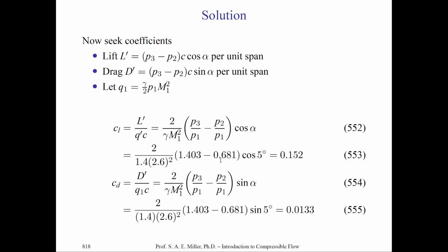We'll now define our dynamic pressure in the classic compressible flow sense, and it might be a good exercise for you to show indeed that gamma over 2 P1 M1 squared goes as, of course, the dynamic pressure in the traditional sense. We'll write that as Q. Perhaps you've heard of max Q during the launch of particular aerospace vehicles, like rockets. Let's fill in our equations now and define coefficient of lift as the lift divided by the dynamic pressure times the chord. And indeed, we've defined a non-dimensional quantity.